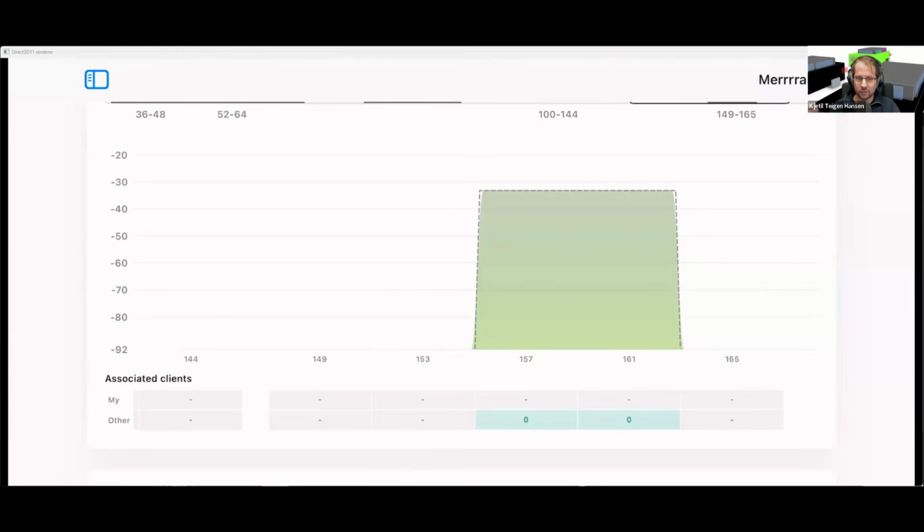And you can even configure a single source to interfere 1 dB below that limit because it's hard coded from the vendor. So if you get 1 dB up, the Wi-Fi completely stops. And then I can just do it. And you can see this clearly because the channel utilization will go up before it. Isn't energy detect even in the 802.11 standard, right? The level of energy detect, Mr. Mackenzie.